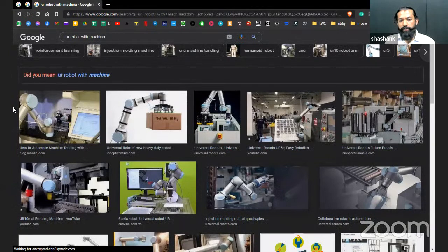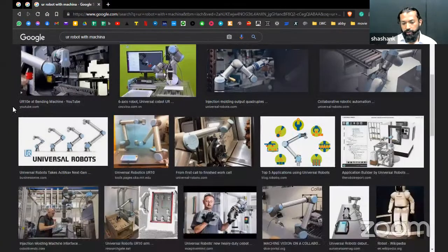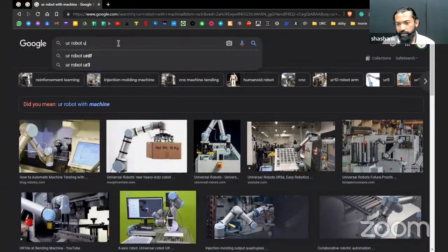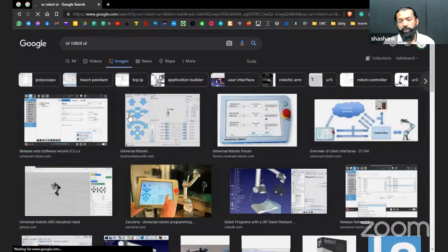The risk to you is far less with the UR robot with its force feedback, where if it was to hit an obstacle, it will stop rather than push through, as compared to some of the other robots that you have. So, very easy UI, easily programmable. The UR language is not as complicated as Rapid or even KRL. So that is something to look forward to.